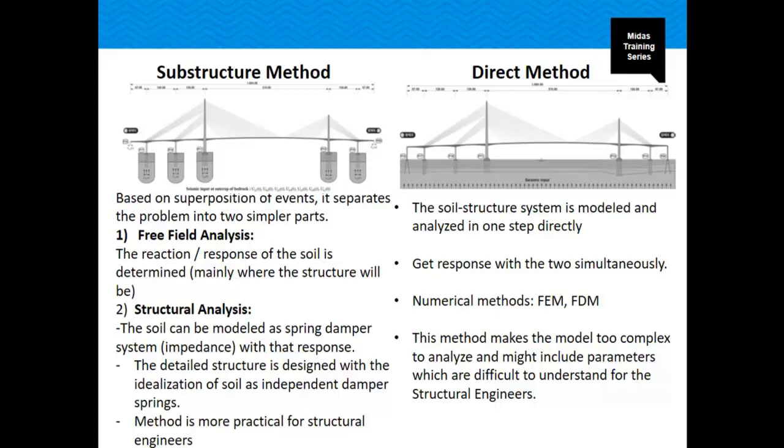Here the soil is modeled with dampers, spring dampers, and then from there you design the structure with the idealization of the soil properties. This is a more practical method for structural engineers. We don't have to go into much detail of the soil properties, since it's just an easier way of performing the analysis considering the soil.